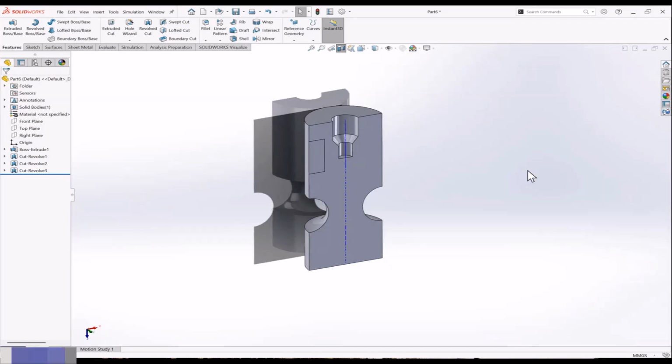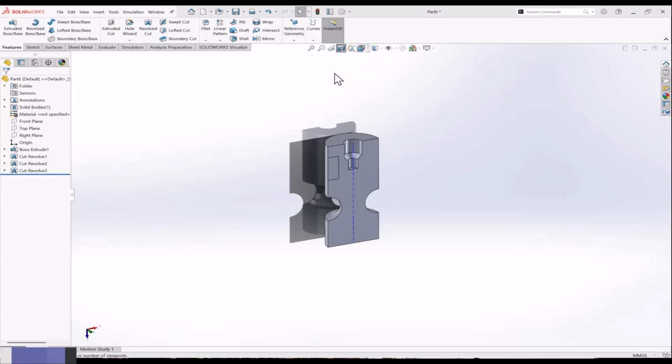Now we'll see the sweep tool. Okay, the sweep tool, what does it do? We need to make one path and one cross section. So I'll just guide you on that. You need one path shape. Any path you can create according to your profile. Like if I want to make a simple pipe or rod, we can design a path. Okay, so what will the cross section be? Generally for a pipe it is a circular section. You can make one section, or we can say a sketch we will draw, or we call it a profile also. We'll draw one profile. Different names you can say. So we draw it and we just sweep along the path. That is what we do in the sweep command. So let's see how to do that.